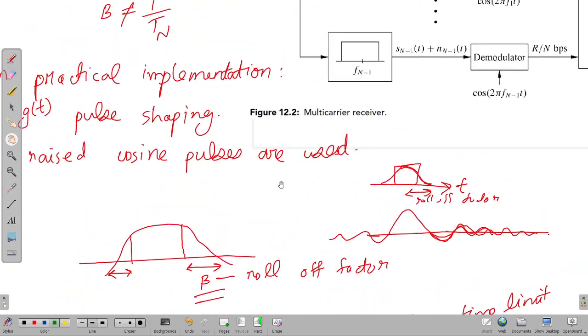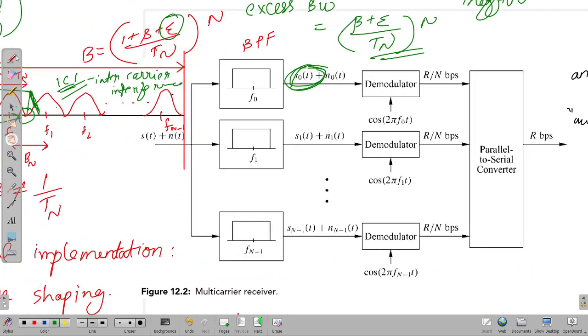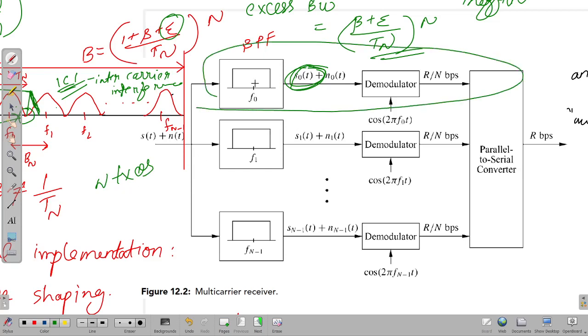And the third point I want to make is you can see how many systems are there in this transmitter and receiver. On the transmitter side you will have N modulators, N of what you usually call chains. These are communication chains. Each communication chain will contain a low pass filter and a demodulator.